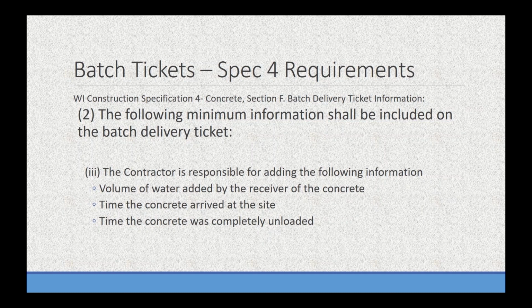And then lastly, the contractor is responsible for adding the following information. A lot of times if we're collecting the batch tickets and checking them prior to unloading, we may be adding some of this information, the inspector at the site. So we're going to need to know the volume of water added before the concrete is discharged so that we can determine what the water cement ratio is, the time the concrete arrived at the site, and then the time that the concrete was completely unloaded. There are requirements in Spec 4 that talk about the maximum amount of time that can elapse before the concrete needs to be unloaded.